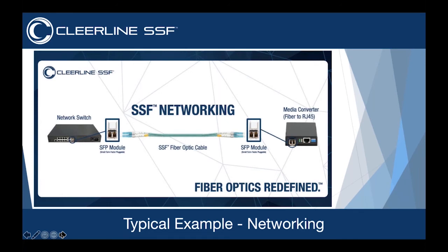And then from there, you've got your RJ45 port to your camera or whatnot. Okay, so a very, very simple application. You need to extend 1 or 2 ports from your main network down a long distance to a security gate or such like. You've now got the ability to do that with latency-free infrastructure. There's no issue with timing here through fiber optic.